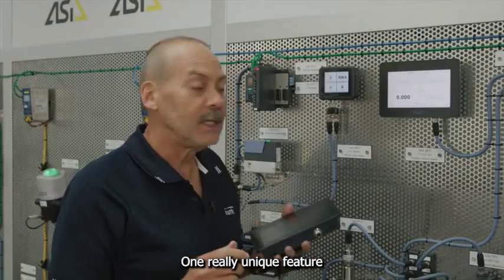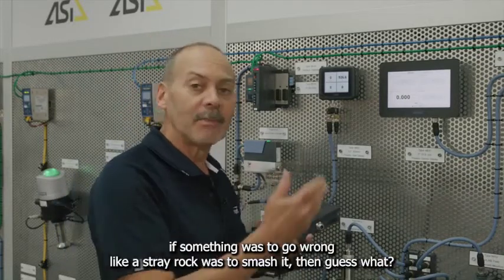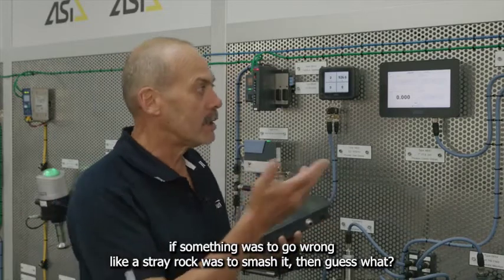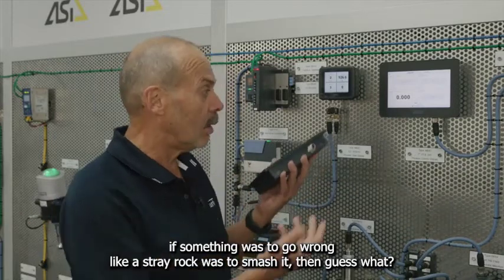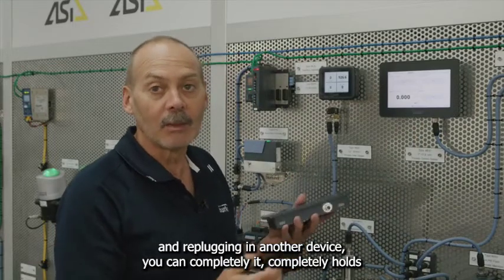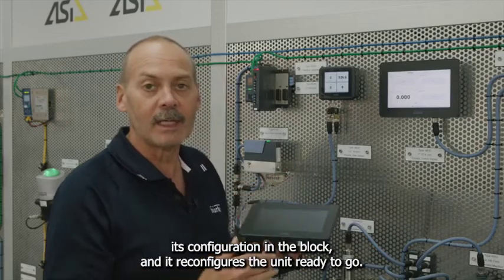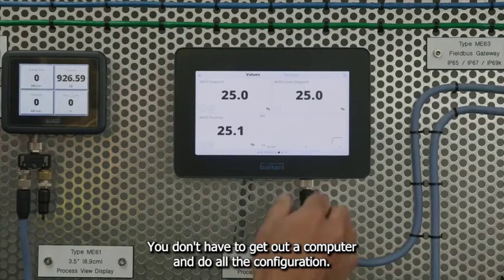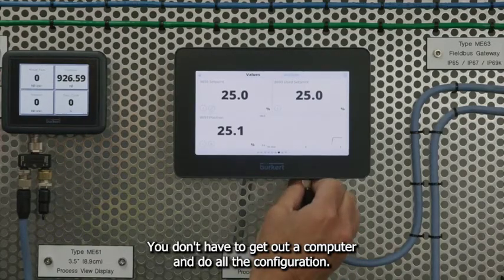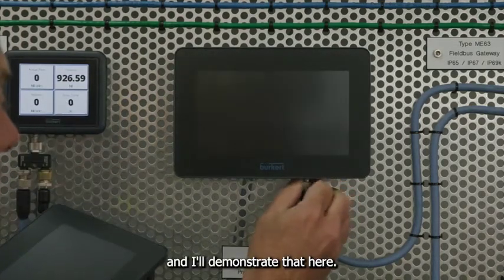One really unique feature is the fact that once it's all installed and programmed, if something was to go wrong, like a stray rock was to smash it, then guess what? By simply unplugging and replugging in another device, it completely holds its configuration in the block and it reconfigures the unit ready to go. You don't have to get out a computer and do all the configuration. All you need to do is plug in a like device, and I'll demonstrate that here.